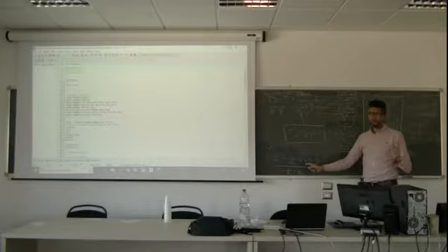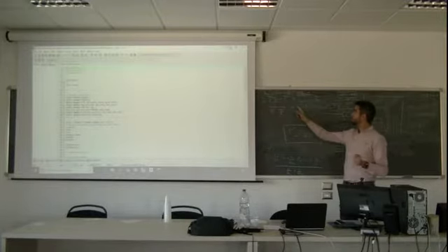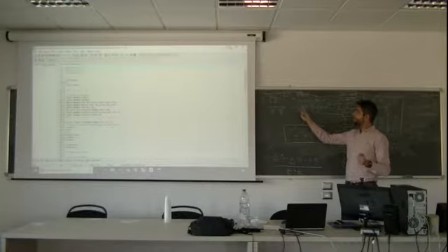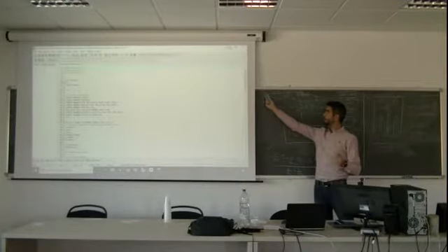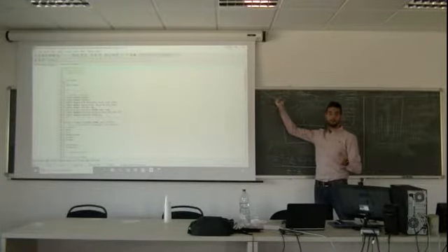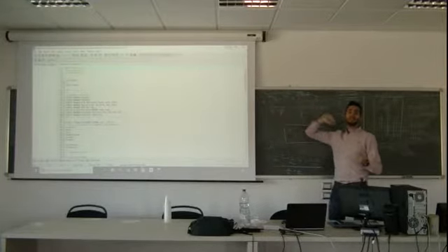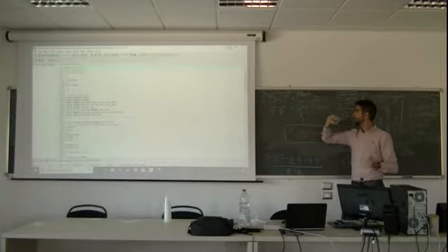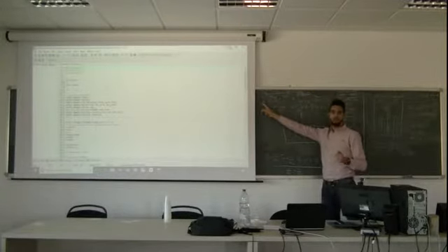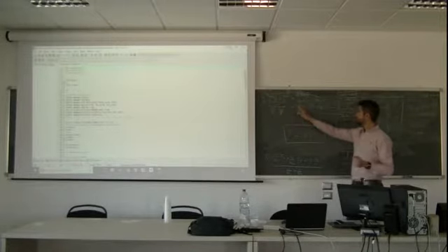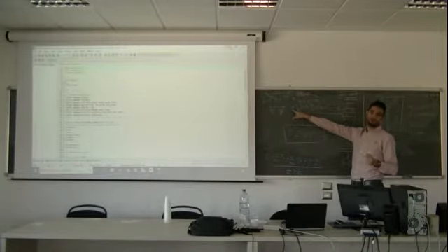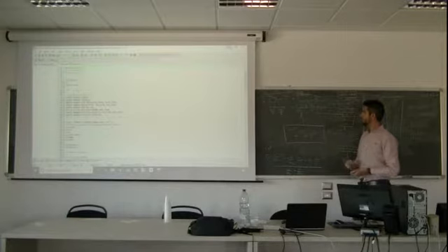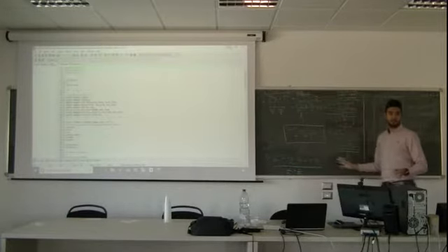That means something went wrong. Probably, remember that when you're computing the heat coming from the west, Fourier, the derivative is the gradient between forward minus backward, so P minus W. And Fourier is minus thermal conductivity multiplied by the thermal derivative over space. So at the end you get always something like this.